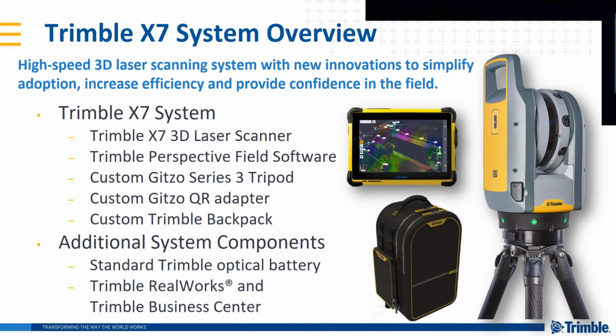and these are the same batteries we're using in our S-series total station. And also with the T10, we supply 3 batteries, and the T10 is such that you can actually hot swap the batteries, so you don't have to turn it on and off in terms of the work you're doing. Other than that, of course, more batteries if you want, but we try to put together a package that gives you the capability to use the scanner all the time or for a whole day's work.